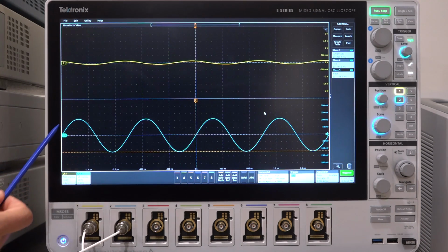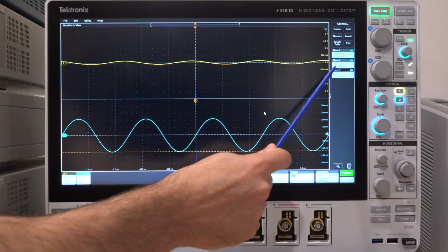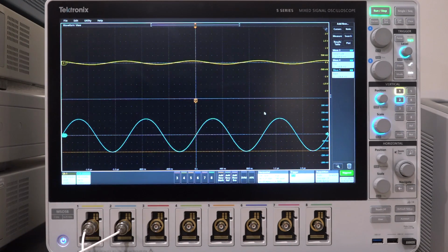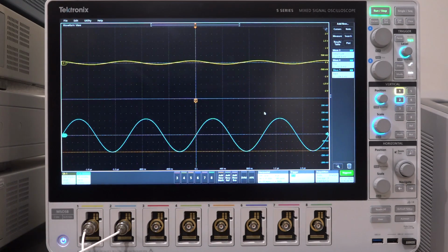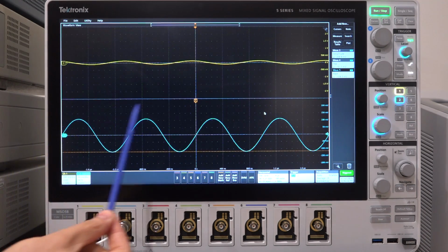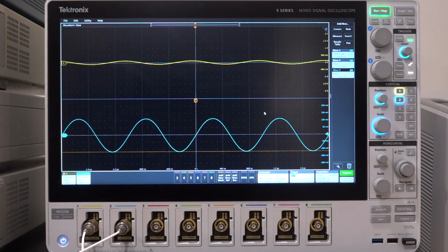So here it is when it is half a volt peak to peak. And if you look over here, the minimum and the maximum values match. And remember, you should multiply those numbers by a factor of 2 because there is a 50 ohm power splitter directly before the oscilloscope. But anyway, you can see the amplitude is 230 millivolt. It should be about 250, which makes sense. But this is when the signal is small, and this is exactly what the InstaView also showed us, that when you apply half a volt, the signal looks perfect.